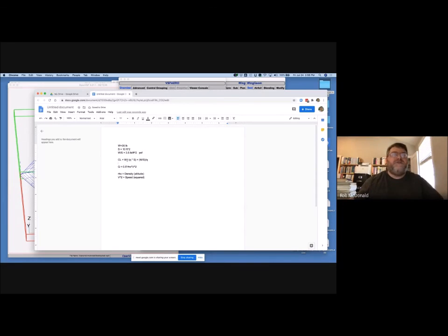Remember I said earlier, pitch for speed. As a pilot flying along, you're trying to trim for some CL. You control CL by controlling trim. You have some control over CL as a pilot, and you want to change your speed, your V squared. There are other ways you could trim. You could trim by throwing weight overboard. You could say, we need to trim this airplane to a different speed, so we need to get lighter, so you throw stuff overboard. That's not very sustainable. Passengers don't like it, and it's hard to go the other way. It's hard to pick up and add weight while you fly.